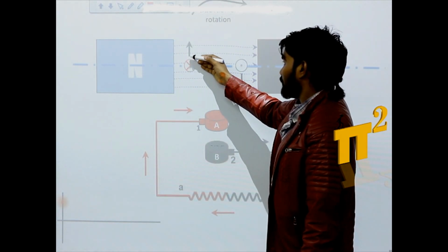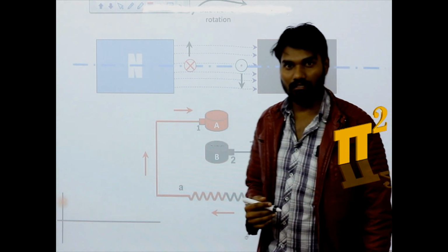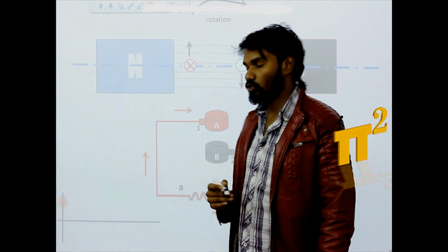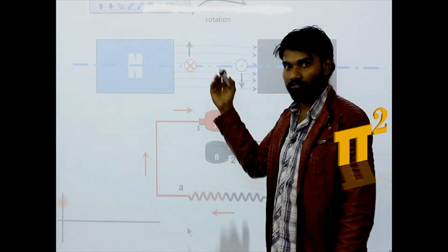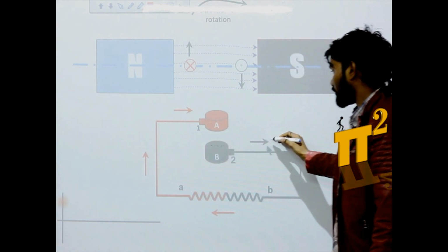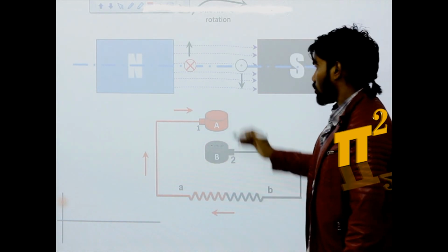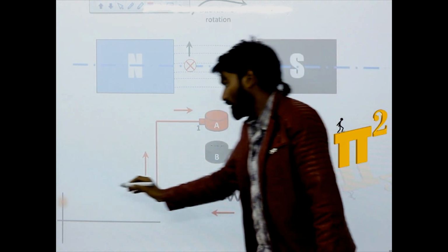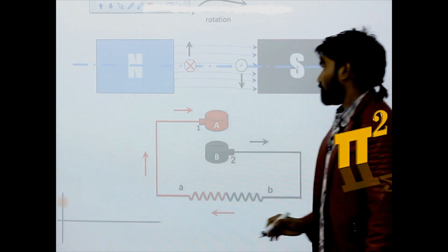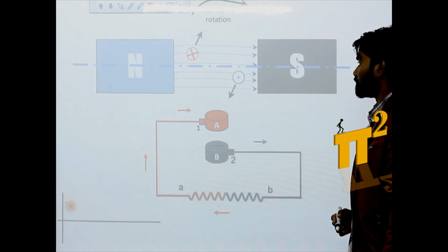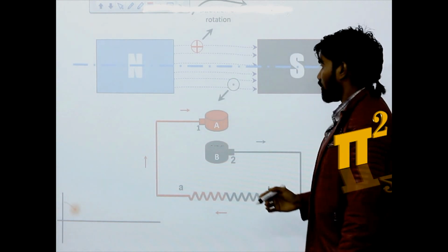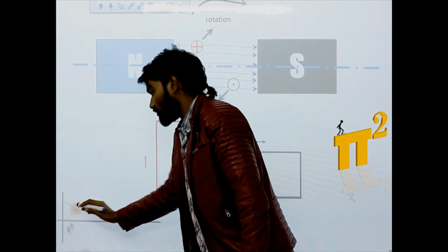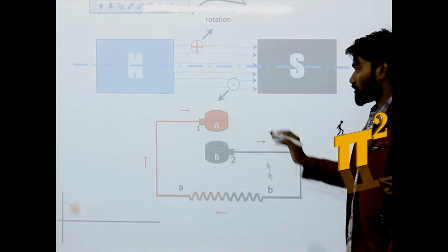As it is taking rotation, we have seen Fy reduces in cosine form, so EMF induced also reduces in cosine form, hence current also reduces in cosine form. So you can see the same rotation, current magnitude and EMF, while it is rotating. You can see the same here. Force Fy is reduced, hence EMF is reduced, hence current magnitude also reduces.